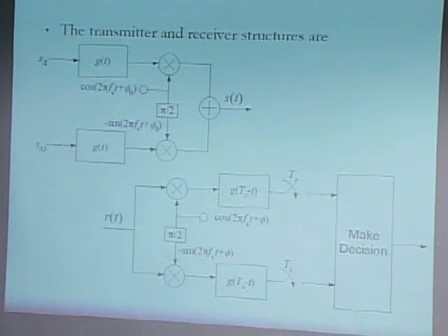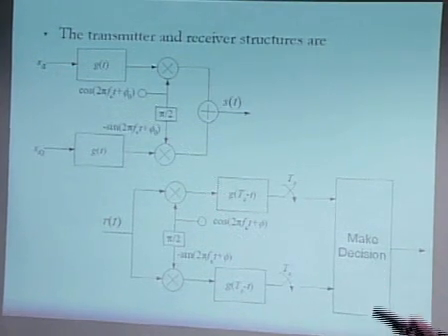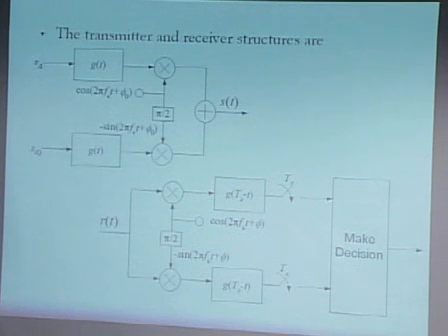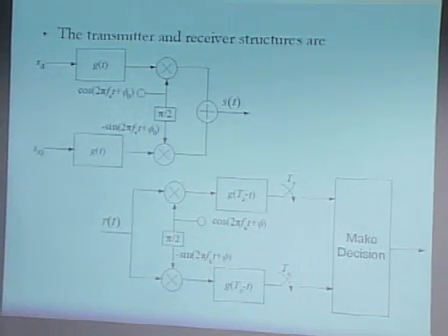So there is a special circuitry in the receiver that actually locks the frequency onto the one that is being used on the transmitter. So this is a very important task, and one that we're not going to have time to cover. So we'll be assuming throughout that this FC is exactly the same as this FC. Okay? So bear in mind that this takes a lot of work, but it is done with pretty high accuracy.